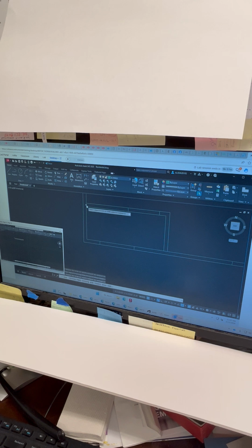if you move off to the side of those objects and just pick one, you get what's called a fence, okay? And then you can use this fence to very quickly and easily trim all of the lines, just like that, with a couple clicks.